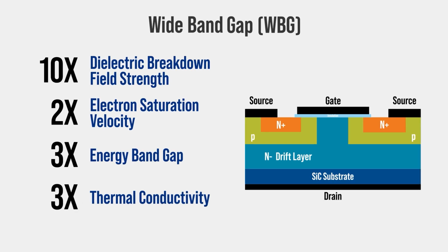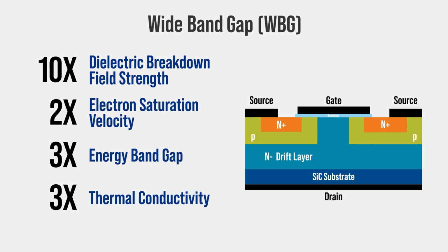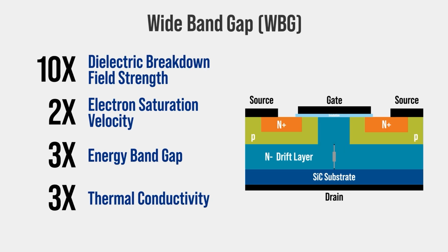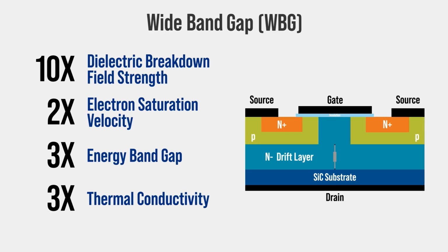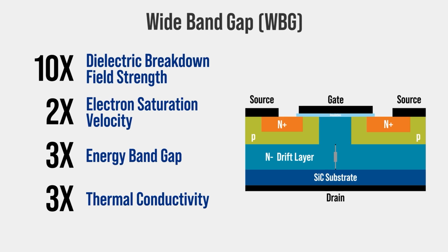Those impressive numbers mean a SiC device has higher breakdown voltages with an even thinner substrate compared to a traditional MOSFET. And then, with that thinner substrate, there is less resistance in the drift layer when conducting. Also, the smaller devices have less junction capacitance. That, along with the higher electron drift velocity, means a SiC transistor can be switched on and off faster. There can be thermal benefits to silicon carbide as well. So it is a switching device that can withstand over 1000 volts with an on resistance down to the tens of milliohms and can operate in the 200 to 400 kilohertz range.